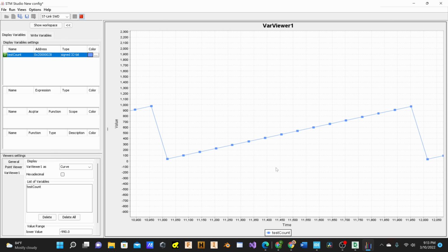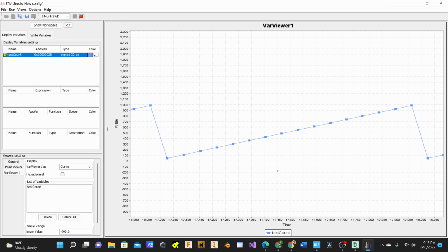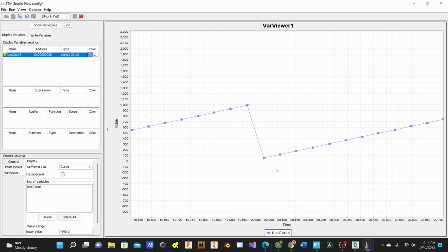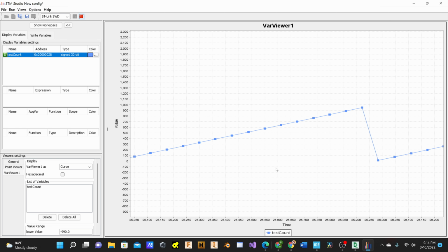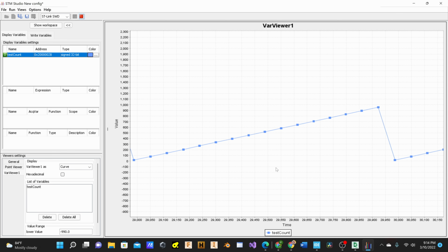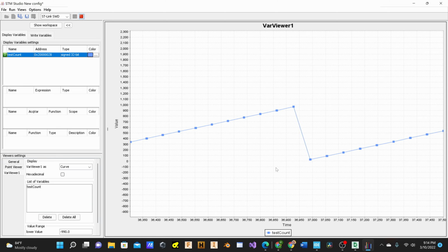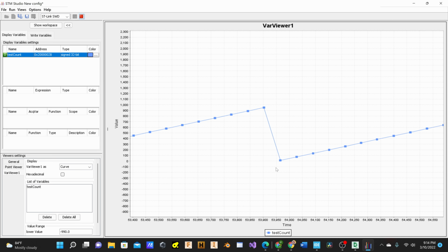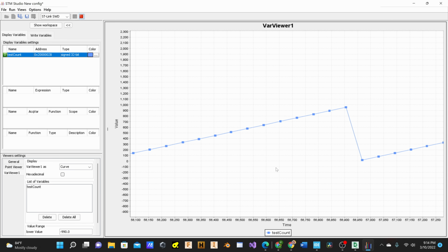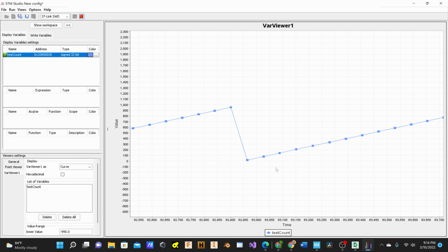So we were able to change the clock speed using the auto-generated code with the IOC file, and we were also able to do it using the register level bit changes to registers. I hope this helps. I am doing this main change to work with the USART. I made this video only to show changing the clock speed because this can be used in any project. So if you need a faster clock speed for whatever project you're doing, use this video to do this.